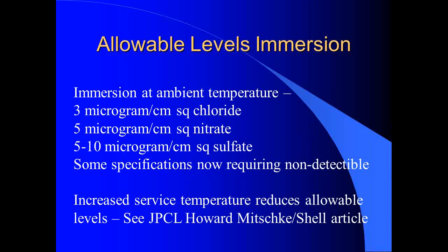Immersion service at ambient temperature: 3 micrograms per square centimeter for chloride, 5 micrograms for nitrate, 5 to 10 micrograms for sulfate. There are also some specifications out there, such as U.S. Naval Facilities, what they call NAVFAC, that are now requiring non-detectable. They started out at 3 and 5 and 10, or 3, 5, and 5, but they have found through the years that it costs just about the same amount of money to obtain non-detectable as it does to get it down to 3.